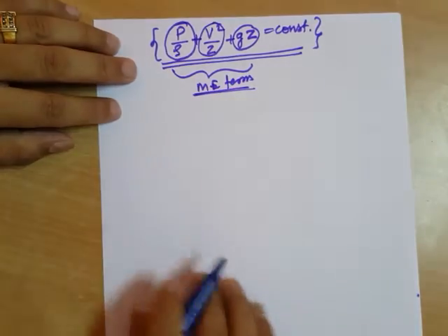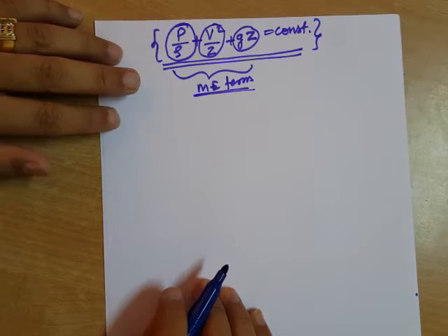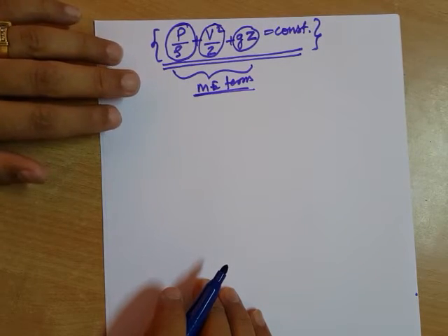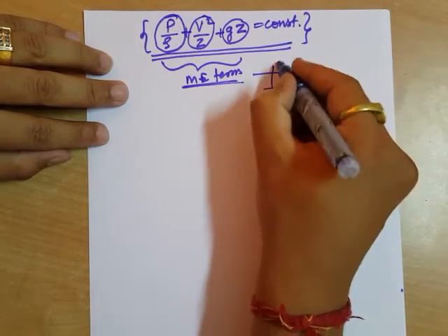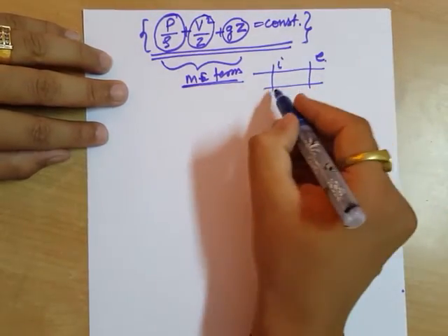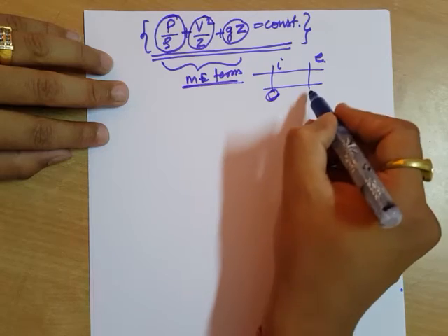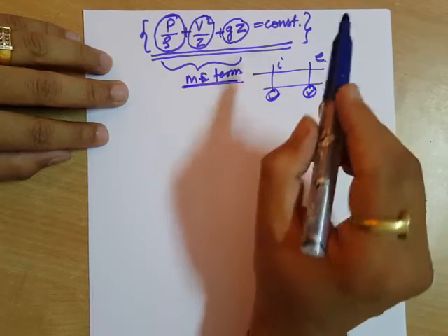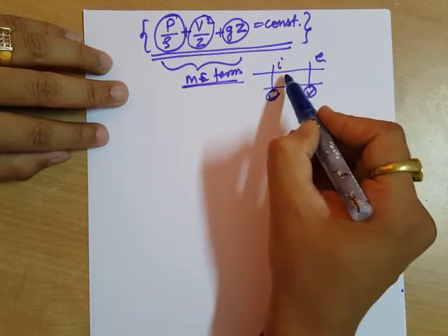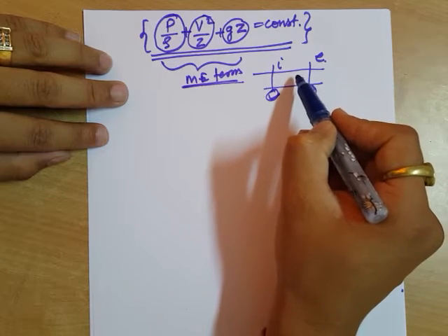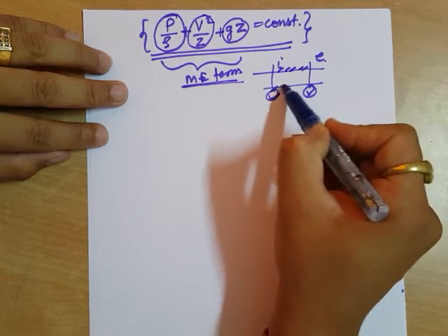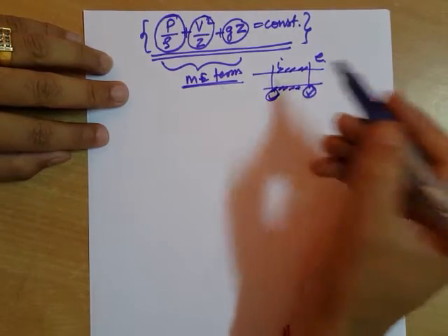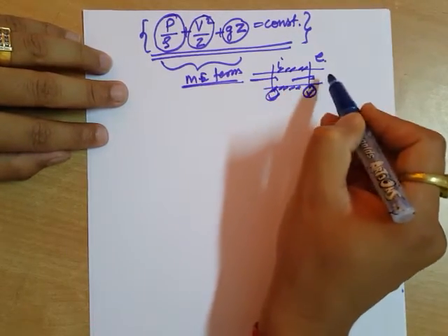So what is Bernoulli's equation basically? Bernoulli's equation is the mechanical energy conservation equation. It says if fluid is flowing from this point to this point, then the mechanical energy here will be equal to the mechanical energy here, provided there is no dissipative effect existing here, there is no friction existing here, and this is adiabatically sealed, and the fluid which is flowing is incompressible.